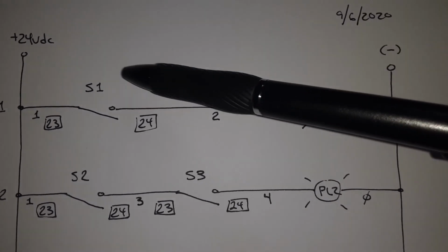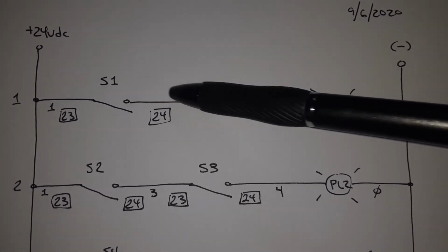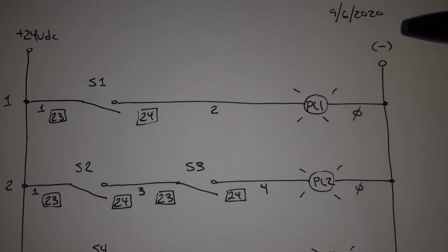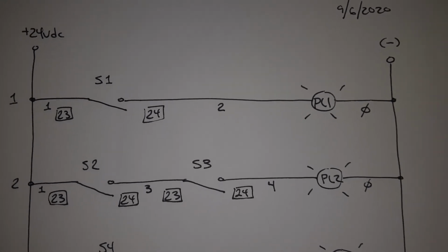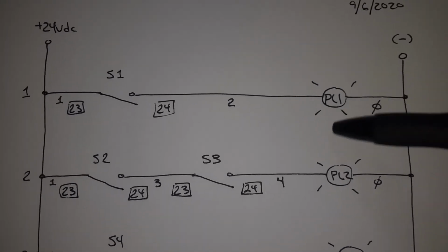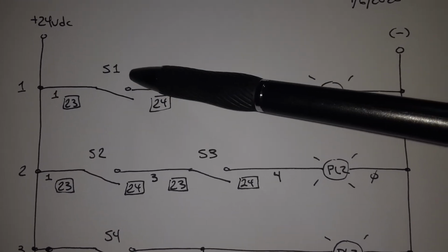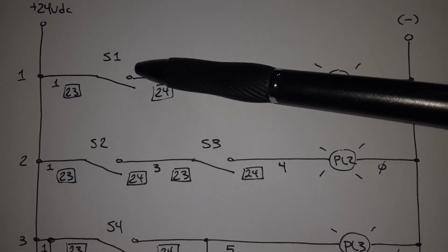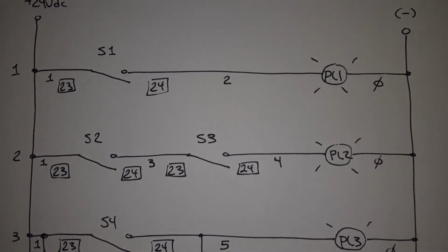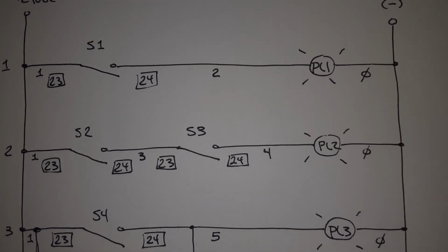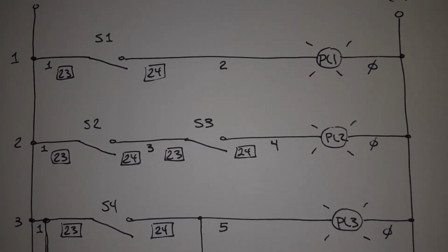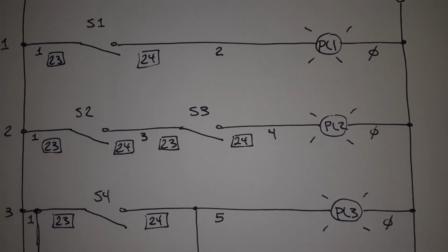So this simple maintained switch logic might be okay for some things, like maybe a lighting system. That's what your wall switch is. Your light switch is a snap switch, on and off. But for other things like motors, it's not a great choice because of that problem of power cycling on and off. So the next video will show 3-wire control logic, which uses momentary push buttons instead, and gives us an automatic reset function. So I'll show you that in the next video.